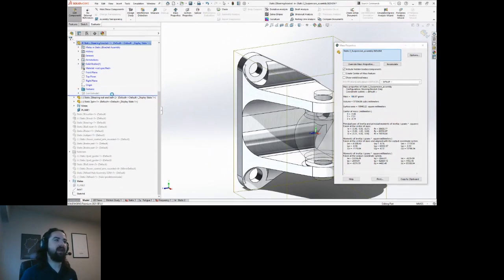And then after adding that cut, if I recalculate the mass, it's 187.27. So just about 2 grams of mass have been removed with this extruded cut. And although 2 grams isn't much to most people, in Formula One, every single gram counts. And so this is the type of weight saving you would see often in Formula One.